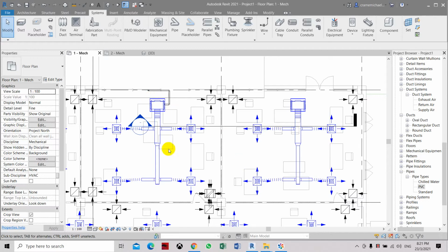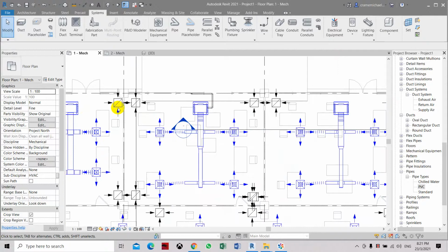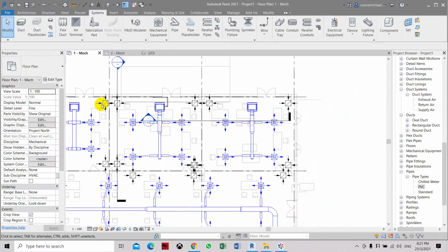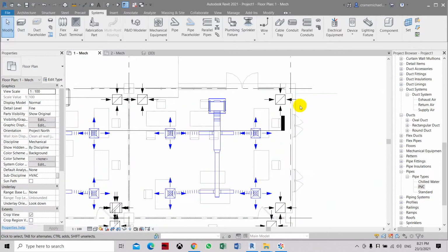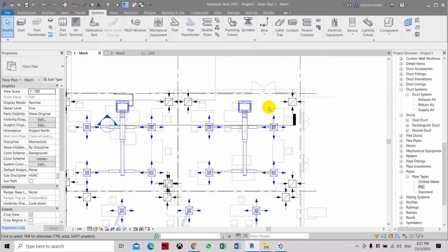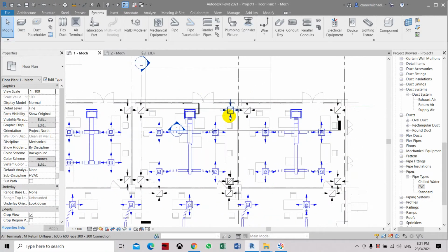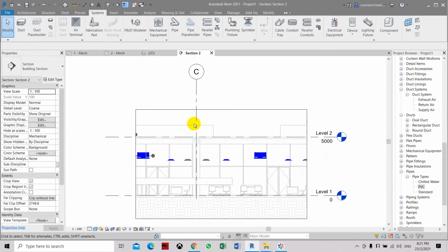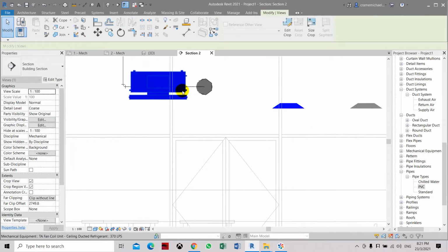We have the two fan coil units. Actually, we have three. So I will create a condensate drain pipe running from this side to this side, and will discharge the condensate drain outside the building on the external area of the building. So I will run it here, from here, here. Let's check the section. What will be the height that we need to connect to the piping.